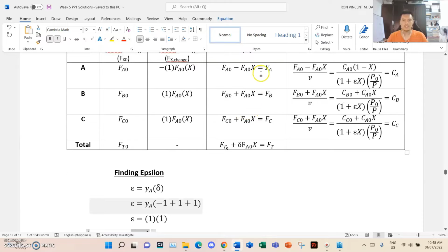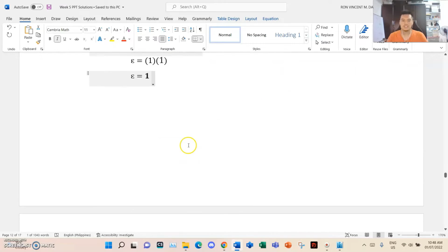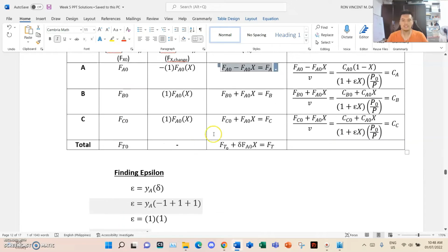And then we need to find the initial molar flow rate using this formula. So the initial molar flow rate of A. We're not given the molar flow rate. So if we're going to simulate this in DWSIM, we're not given inlet stream details. We're only given product stream details. However, DWSIM is a simulator that does forward calculation. So in order to do that, I need to calculate manually the molar flow rate of the ethane.